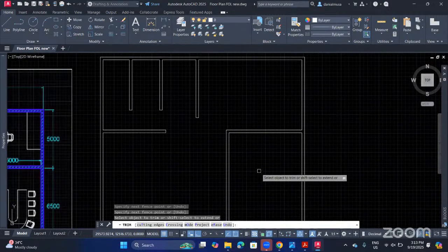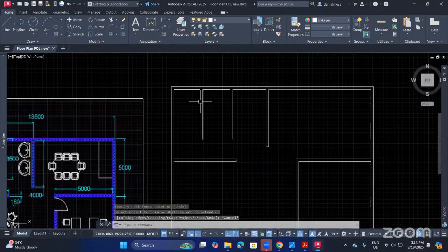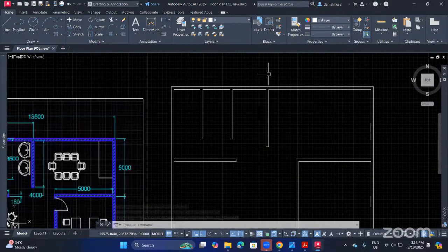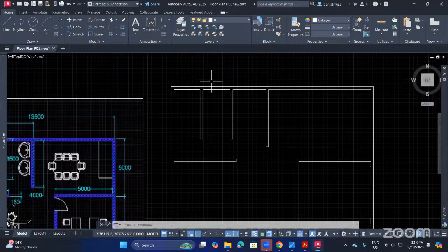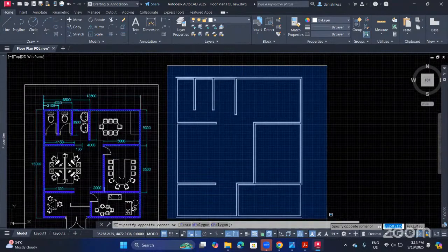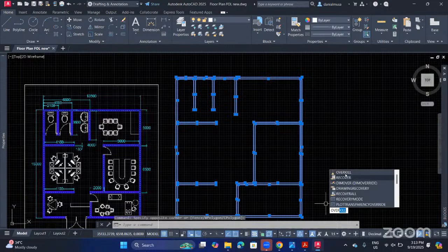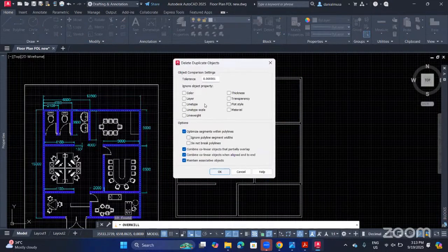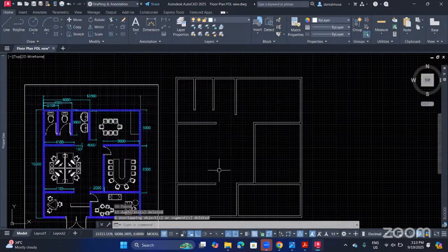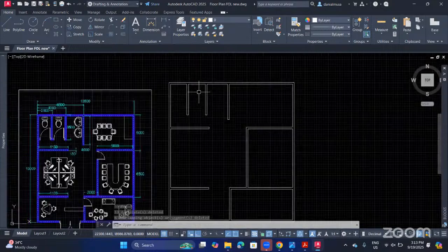I think most of them we have removed, but if you look properly, you can see here is a multiple line and here is a single line. So if we want to make the multiple line into a single line, we can cover it with this. Or you guys saw the overkill, you just click it. This overkill will make the multiple lines into a single line.